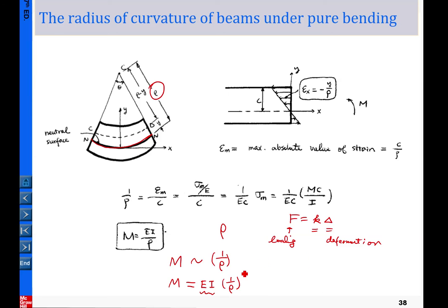The similar concept here is that the given loading, in terms of a moment, M, equals EI times the curvature. You can visualize the curvature as describing the deformed beam, and the EI plays a similar role to the spring constant K. So it gets clear: we have the given loading, we have a way to describe the deformation, and EI is simply an equivalent spring constant for this system.